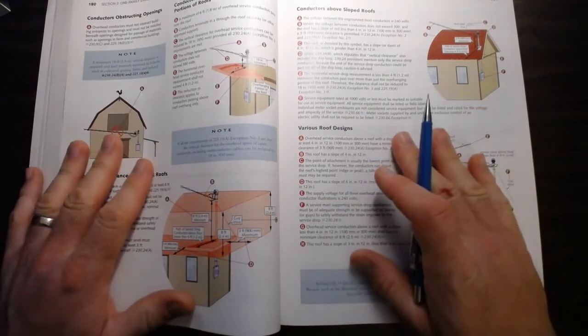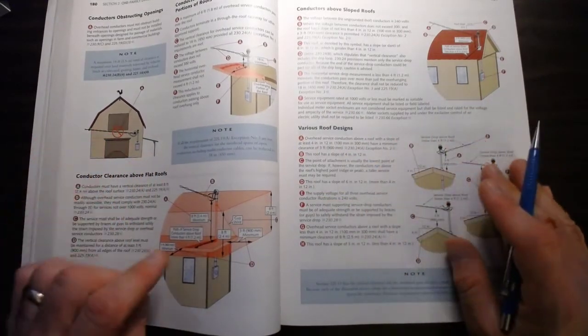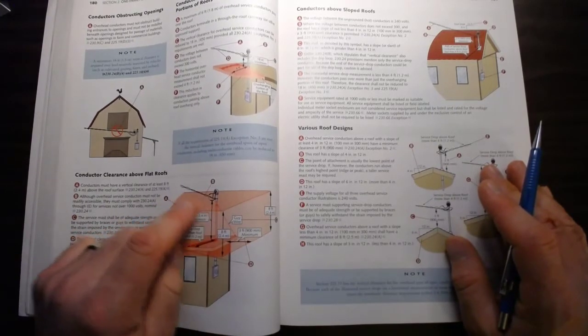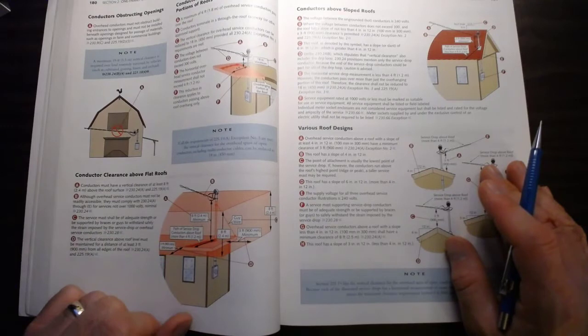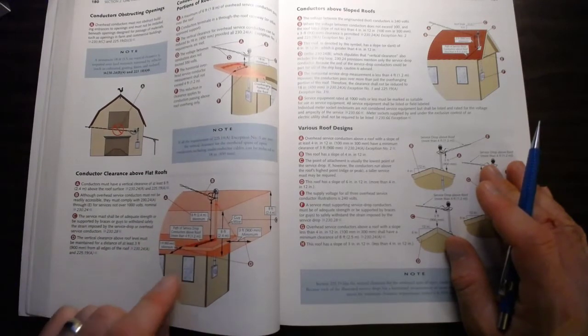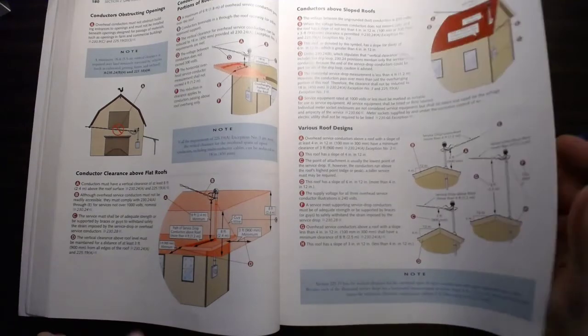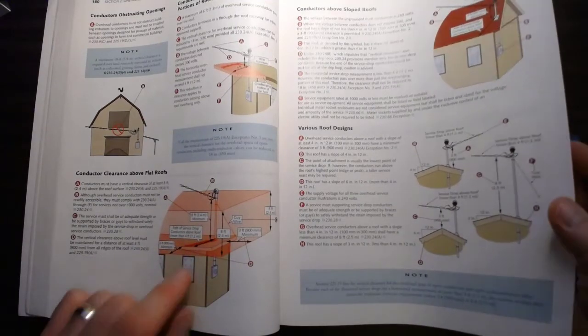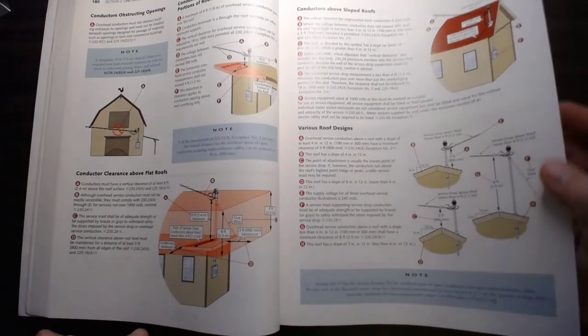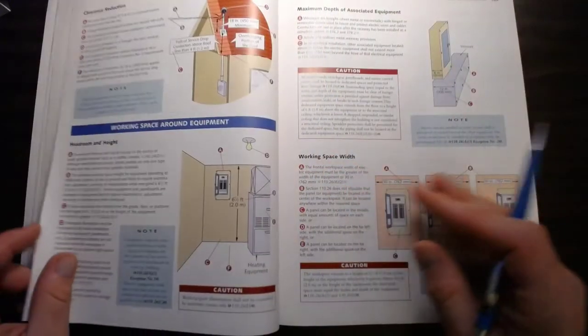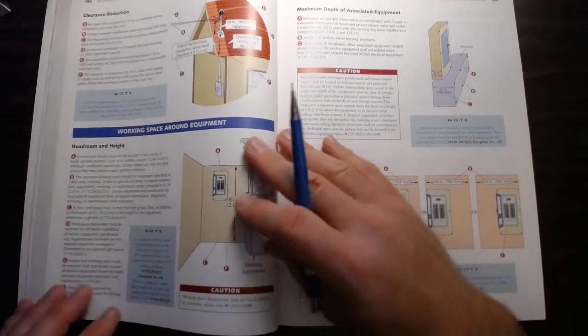If you think about this, you are going to realize that if I'm on a flat roof, I need to make sure I maintain enough clearance so that I can't touch that location, 8 foot minimum in this case, from being on the roof. So think about it: you could set a ladder up there. There's a lot of things you can do on a flat roof that you can't do on a pitched roof. But look through these and understand them specifically.